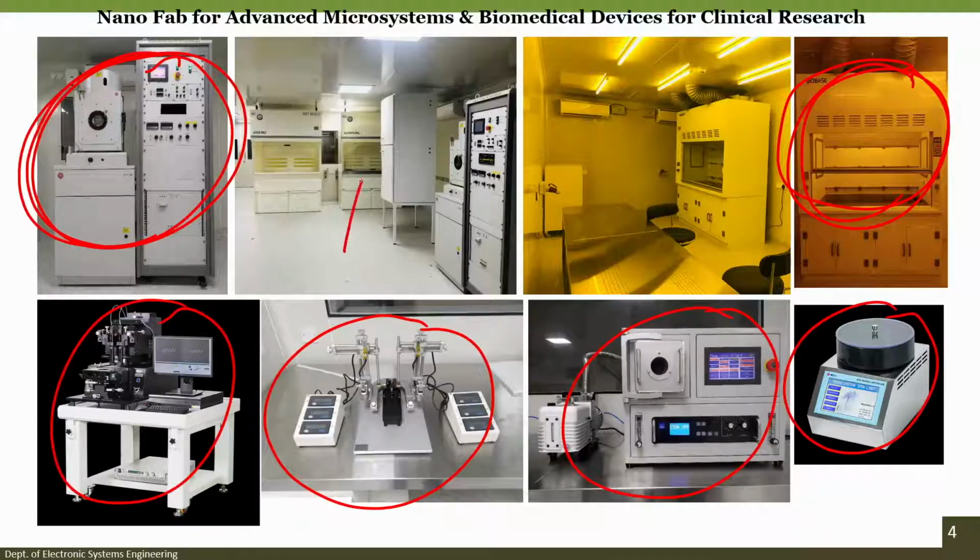If I want to etch the substrate, if I want to remove some part of the substrate, there are two techniques. One is called wet etching and one is called dry etching. In wet etching, there are two hoods or wet benches that are used. One is for acid and one is for solvents. We cannot mix acid with solvent and vice versa. If you see this slide, you can see here we have a solvent bench and we have the wet bench for using the acids.